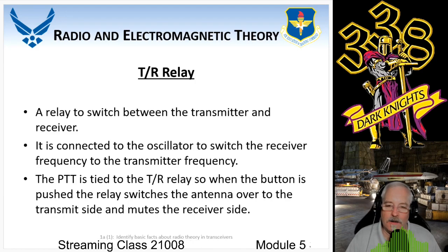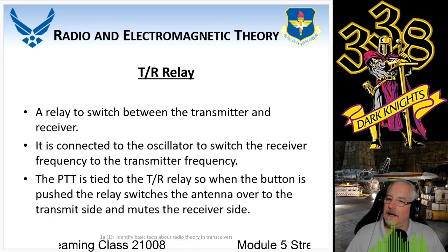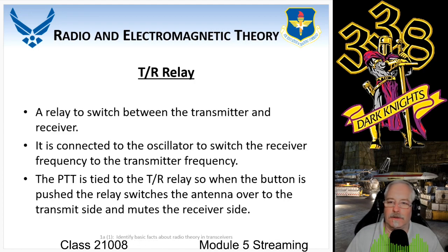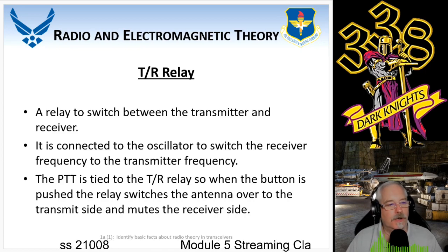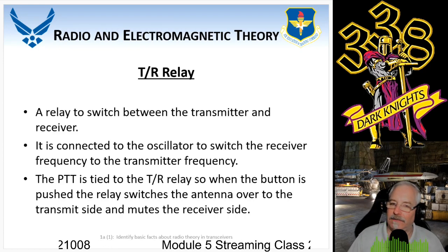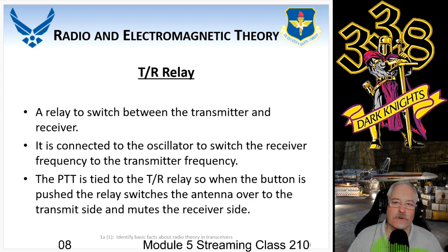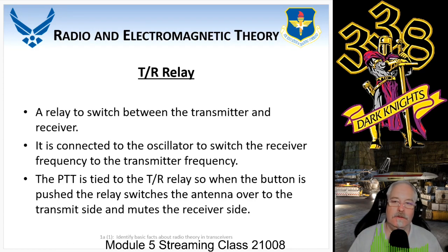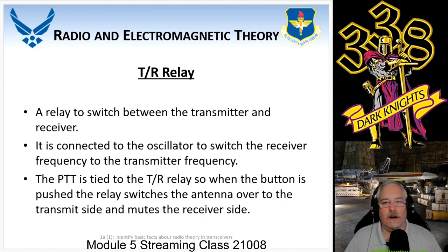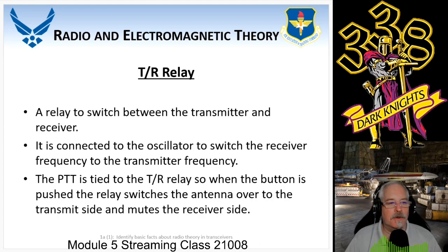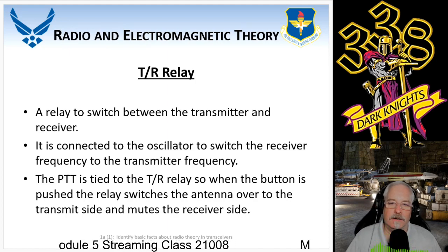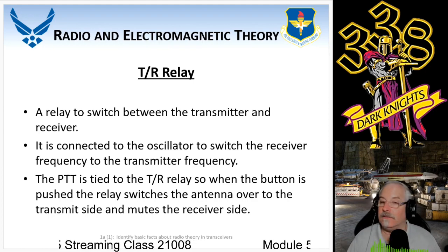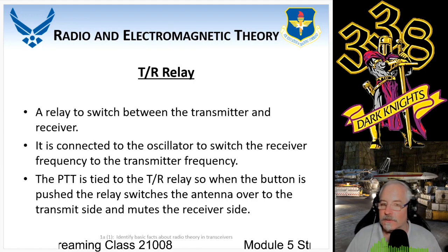Also, if you're in simplex, normally the oscillator used between your transmitter and receiver pulls dual duty, but if you are in half duplex, that oscillator is going to switch frequencies. So the moment you press that switch, not only are you controlling that transmit receive relay, but you're also controlling the oscillator. Basically you're changing frequency from the receive frequency to the transmit.